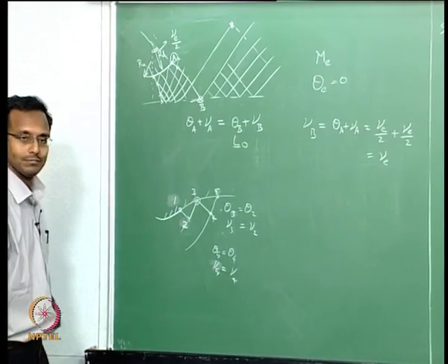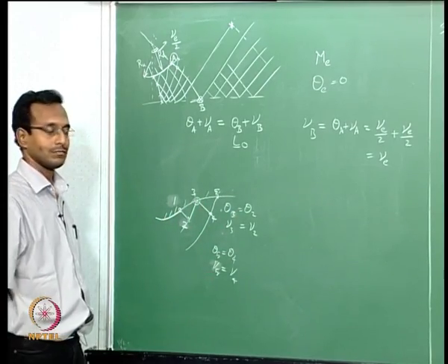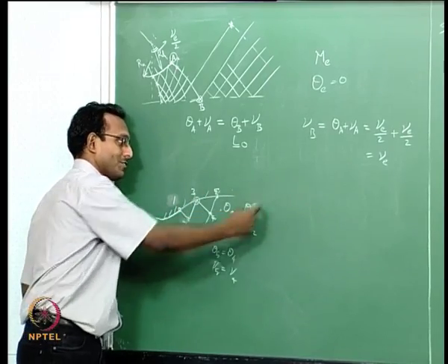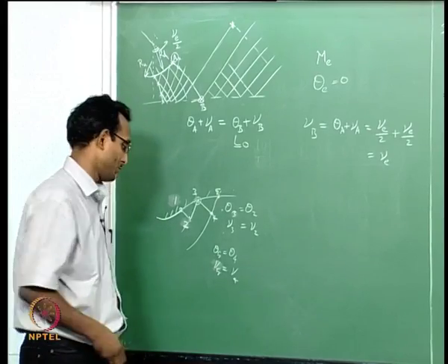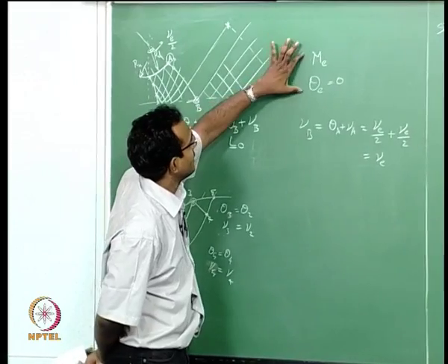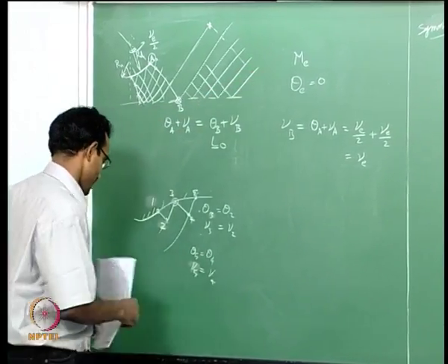I will get to this. This is the way you will create this whole curve. Okay. And once you get this surface, we have solved and we have created a new nozzle which will give me that desired exit conditions, theta e equal to 0 and me exactly that value.